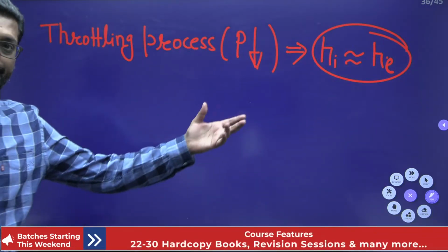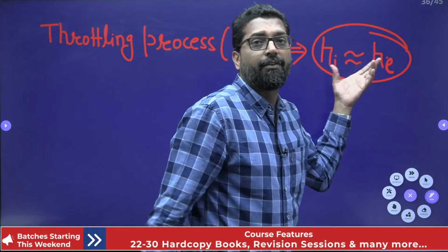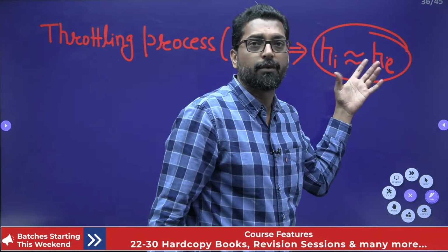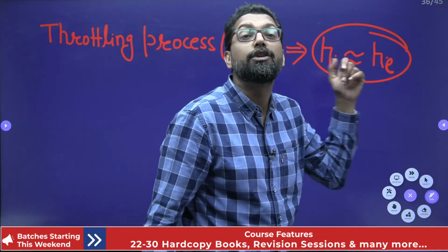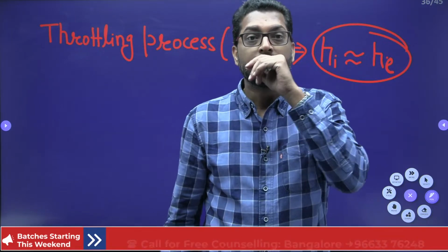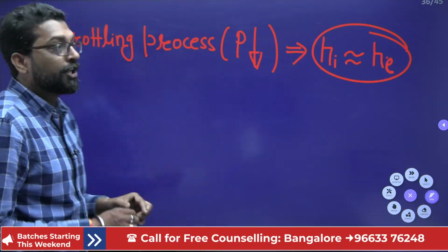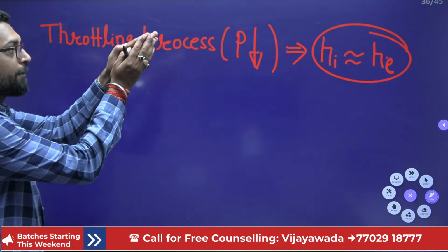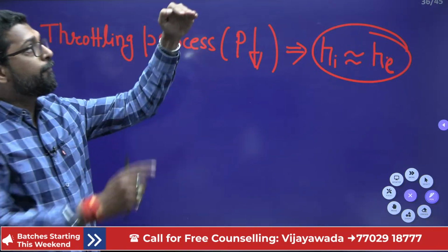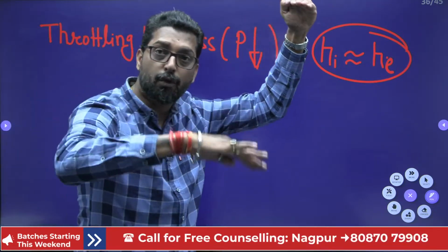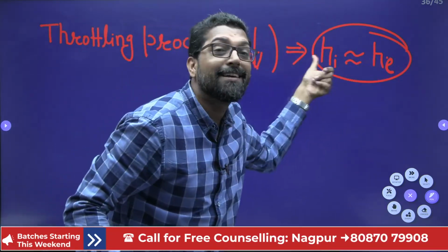That means there is no sacrifice of the energy component with the reduction of the pressure. This is the beauty of the throttling. That means you reduce the pressure of the fluid from a high pressure to a low pressure with the same energy.